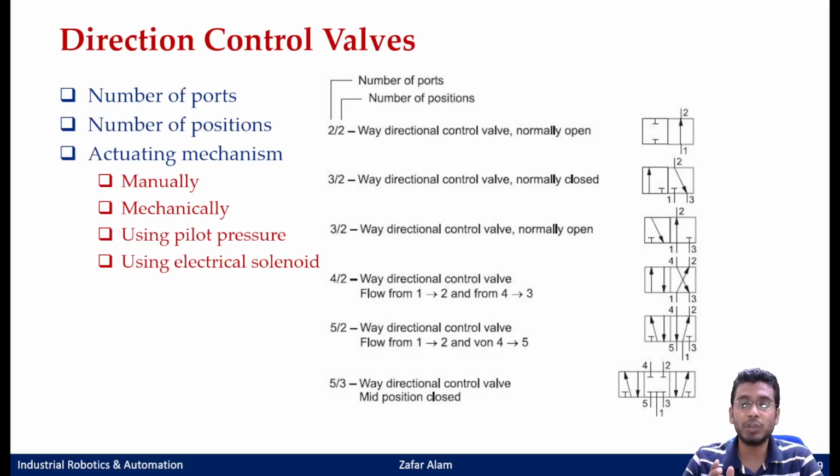Why do we require 3 positions? Suppose I have to control a double acting cylinder. Why do I require 3 positions? Because if I have 2 positions, either the cylinder would extend or the cylinder would retract. What would happen if I have a 3 position valve then? Sir, the flow will split to 3 different. Of course, no.